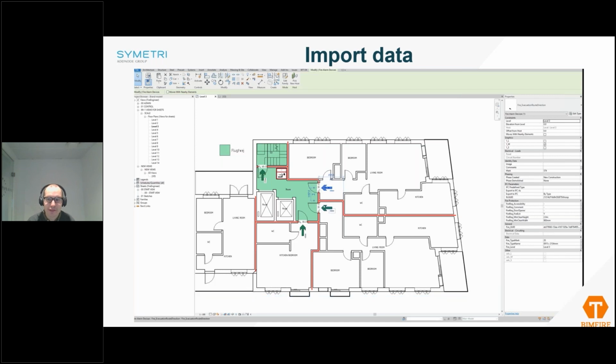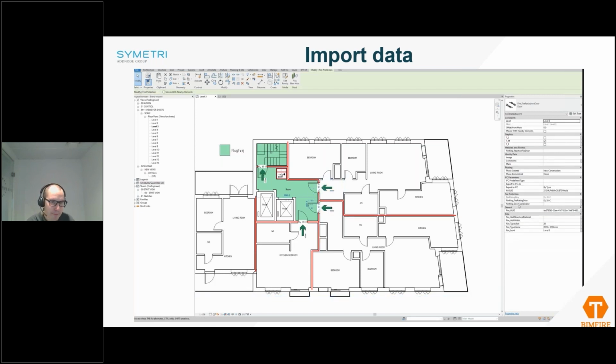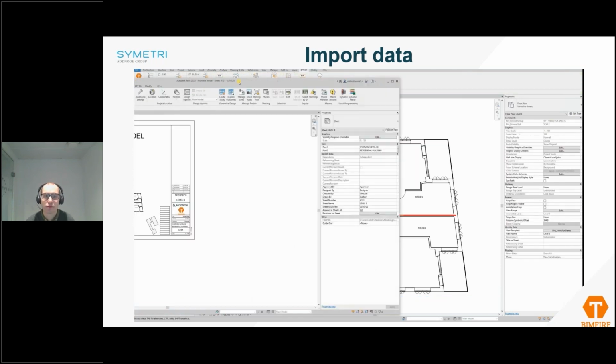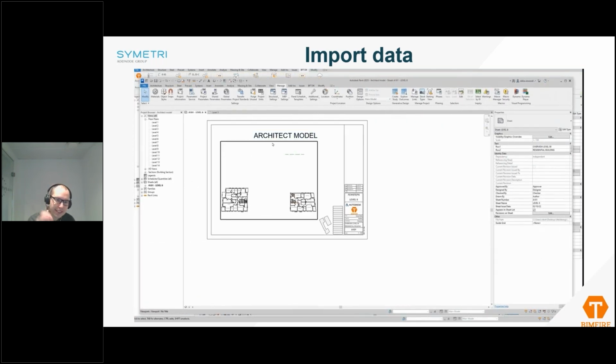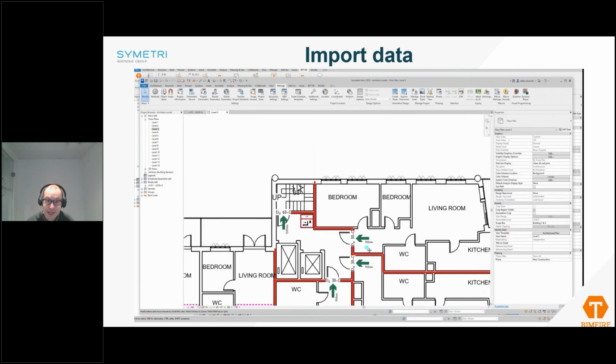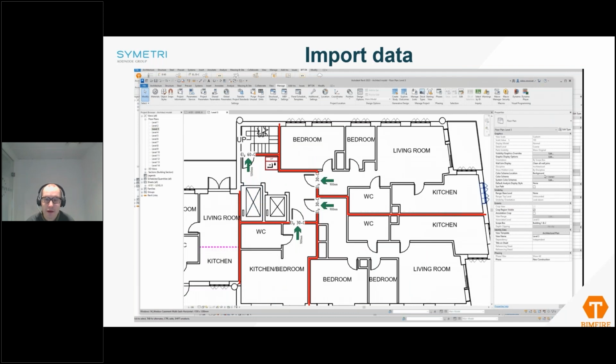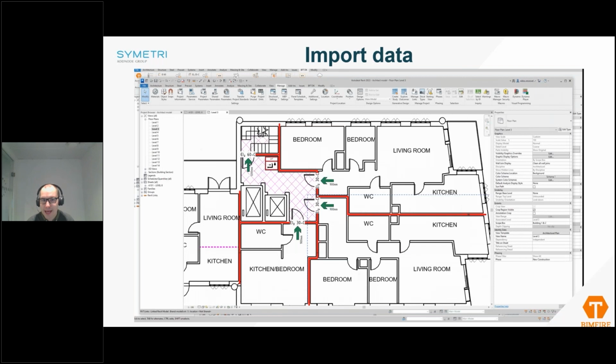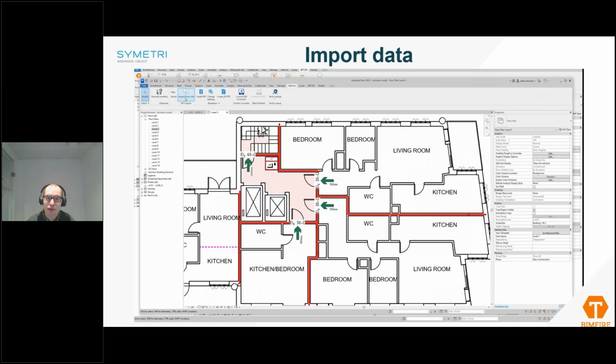Once again, I'm going to let this loop one more time. The different requirements that the fire engineer is adding into their model, creating those PDFs, you will see them perfectly fine in your model as you linked it once again, and you can pull that data from that fire safety model into your model, because you want to use this data on your door specification sheet, you want to show this on your floor plan, etc. as tags or in schedules. You can now use this.